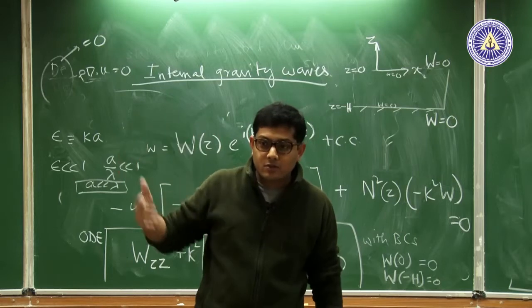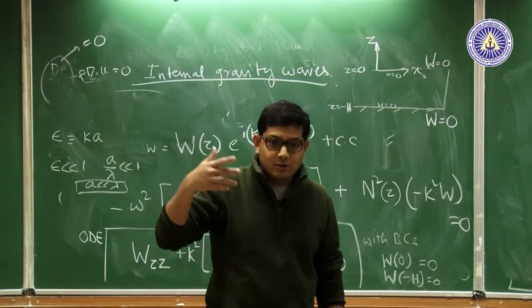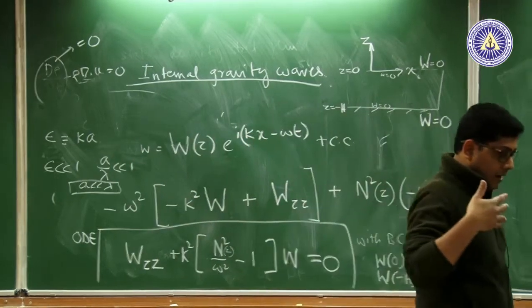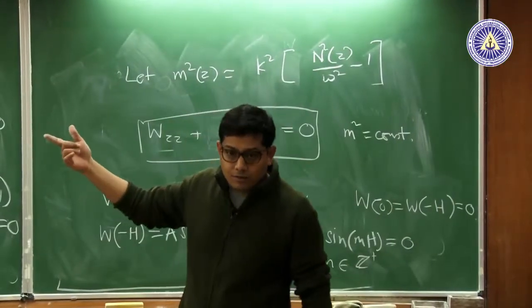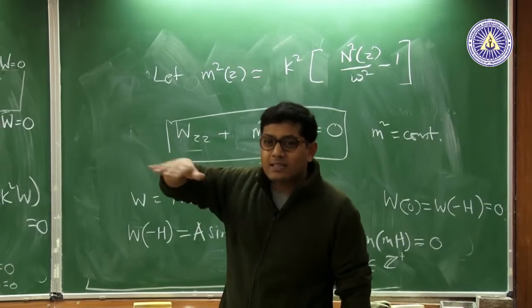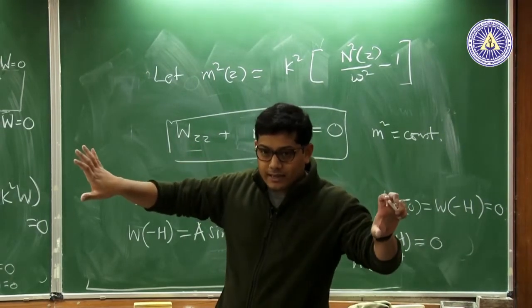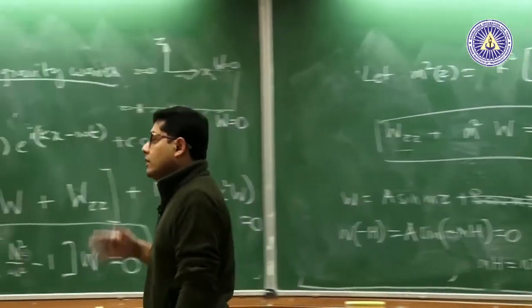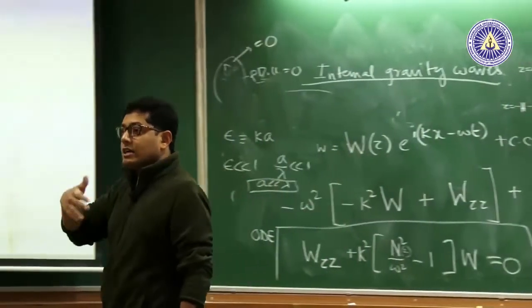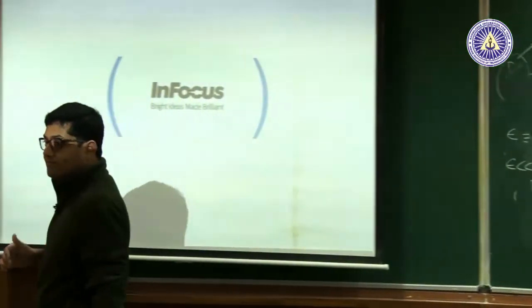It is just the order epsilon square response, a particular solution where the free surface has some undulations but travels along, so this deformation keeps on traveling. But the other thing is that the surface gravity waves travel very fast.